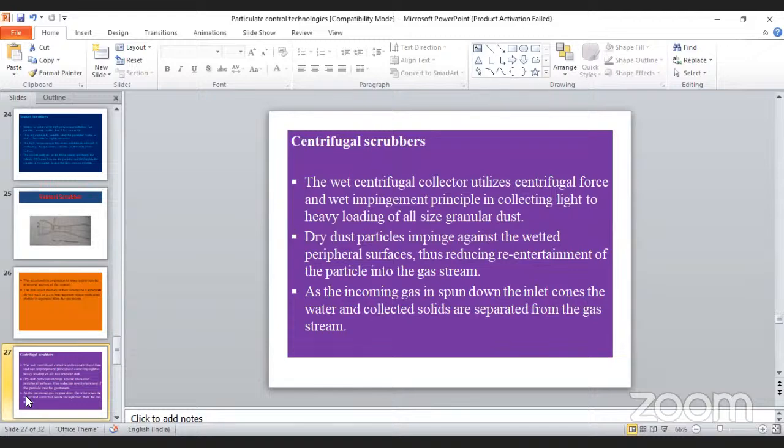The inlet pipe is inside the solvent, and the outlet pipe is just above the solvent medium. Whatever substances can be collected in the solvent medium are collected, and the remaining things are exhausted. This process of cooling down and collection of a gaseous stream is called impinging.